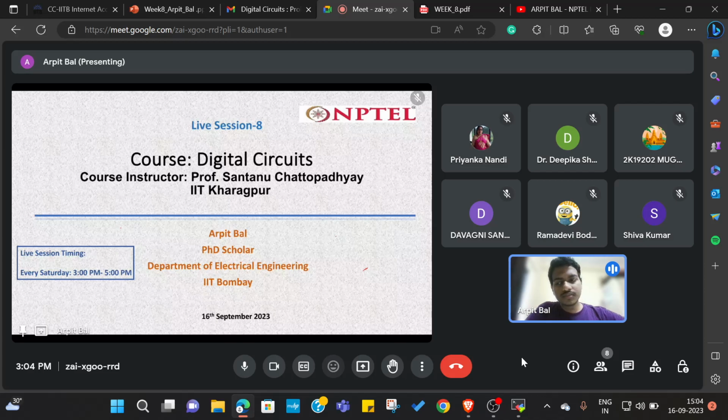There are a few advantages where Mealy machine is used, and a few advantages where Moore machine is used, right? Mealy machines need fewer states, and they react in the same cycle, so they need not wait for a clock, right? But Moore machine is actually a bit safer because the output changes at the clock edge. So that is Moore machine.